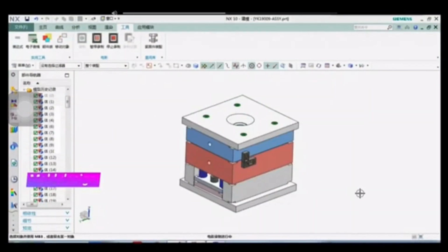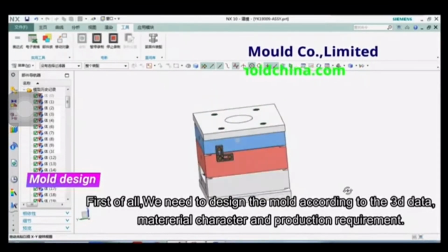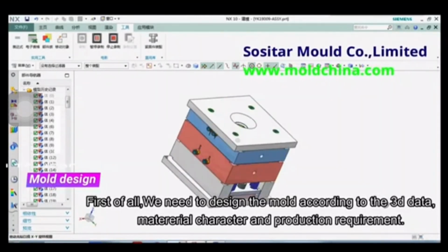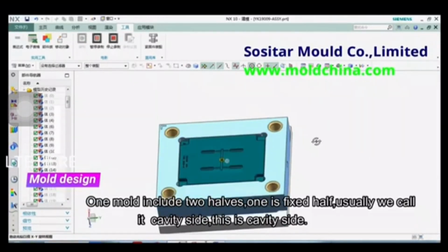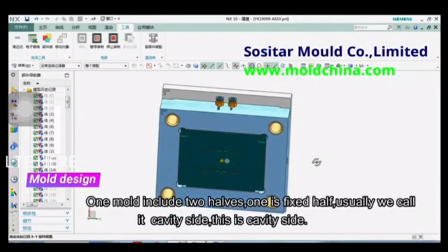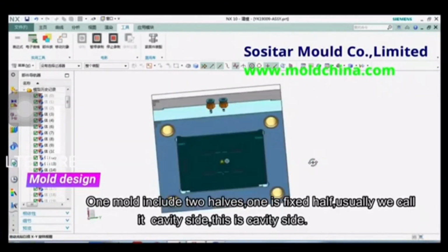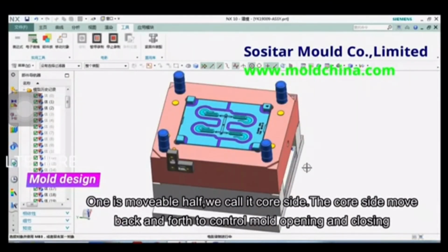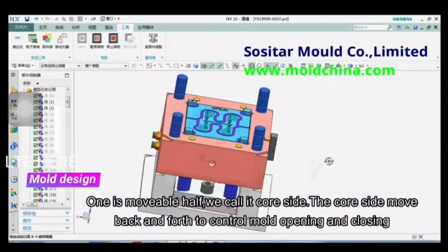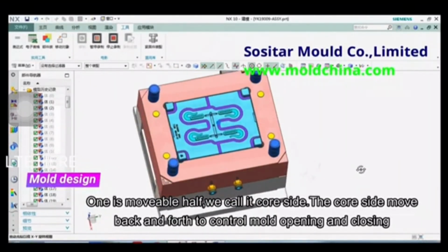So the second disadvantage for injection molding is that careful design is needed. Plastic molding needs very careful design to avoid tooling issues like undercuts, which will send up tooling costs significantly, locked-in features and not enough draft. The material and temperature will need to be taken into account in wall design, otherwise the mold may not fill fully. The placement of ejectors and cooling lines will need to be considered to ensure the product is aesthetically pleasing.